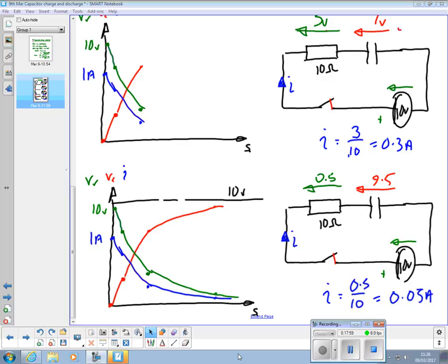But the formula for it says that the capacitor voltage can't reach 10 volts precisely, the current can't fall completely to 0, and the resistor voltage can't fall completely to 0 either. But to all intents and purposes they do. And there is a point in that cycle where by convention we say the capacitor is fully charged, and at that point, I think, we'll calculate it later, but I think that's something like 99.5% towards that full 10 volts if that's what you're applying.